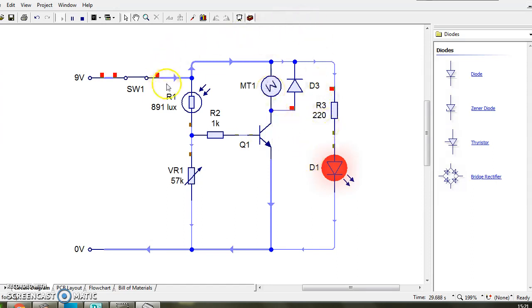My LED is on anyway. And if it gets dark because I'm above the line, then my motor stops turning because my voltage here is now down to 7.749 volts. So that's dropped down. So I now know that that will turn this on and off according to the circuit simulation, and that my LED will turn on and stay on all of the time.